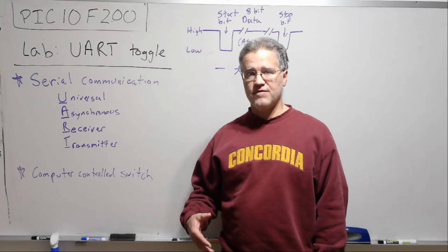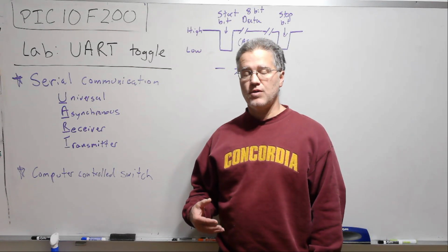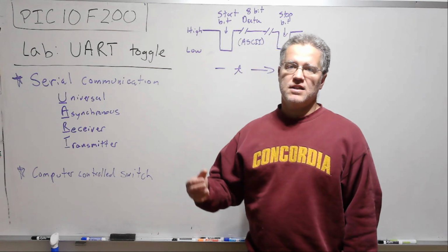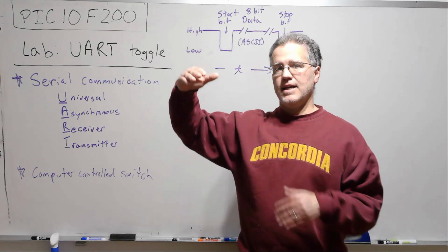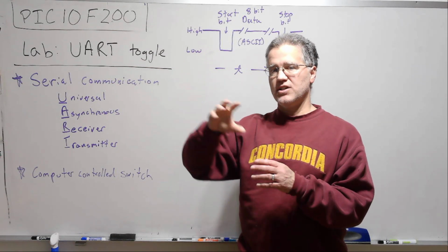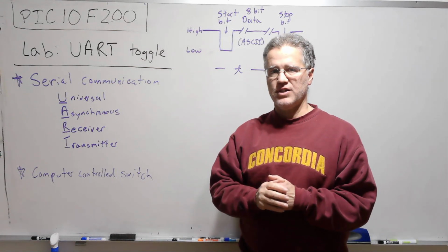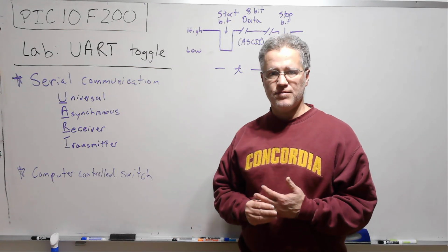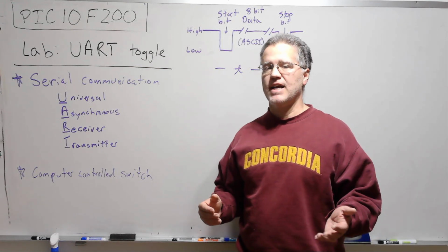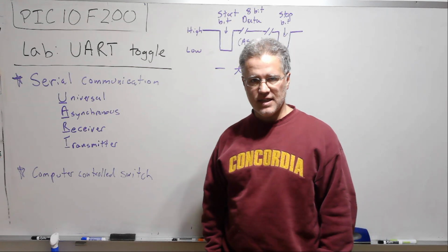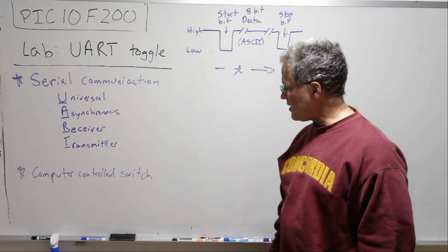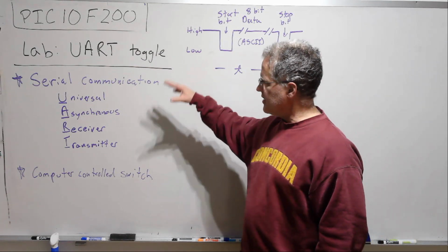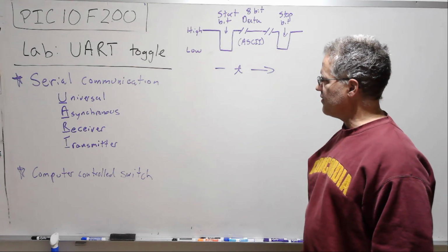We're going to just turn on and off an LED, but in the lab, I actually use it to turn on and off a MOSFET that then acts as a switch for a much higher voltage optical shutter, for some of the laser work that we do. And that's driven by a solenoid, so it needs 26 volts and 250 milliamps, so well beyond what the PIC can provide, but definitely within what a MOSFET transistor can apply. And so using these in tandem has been very helpful for me.